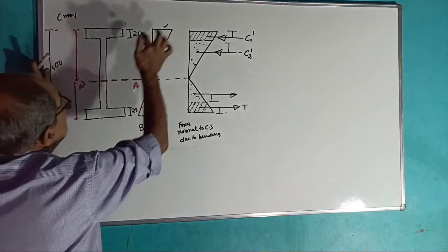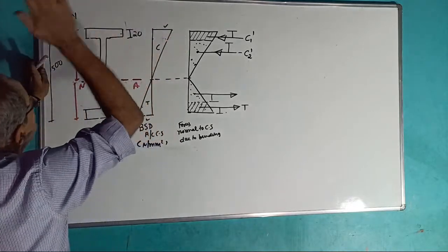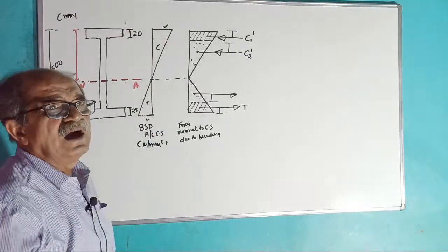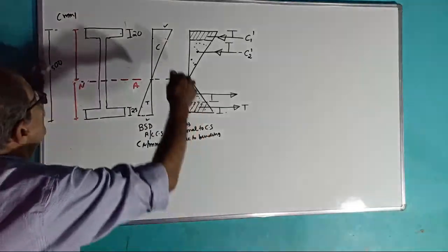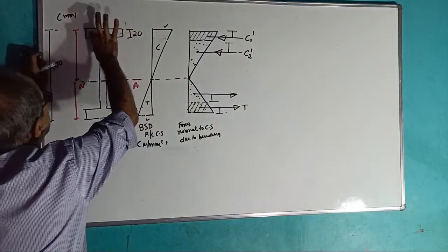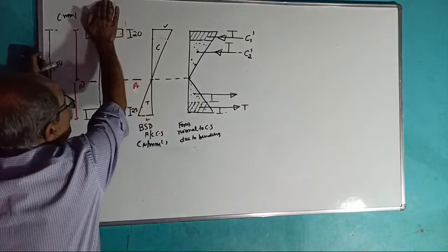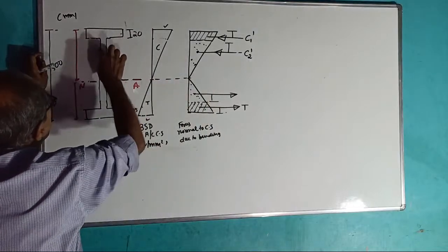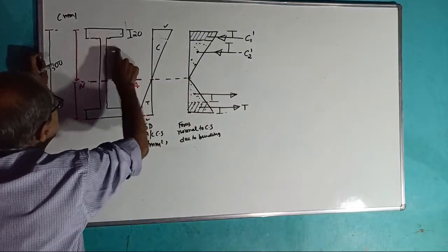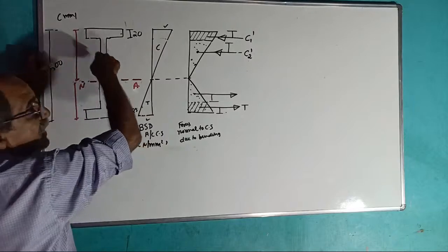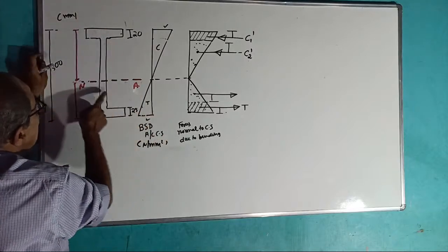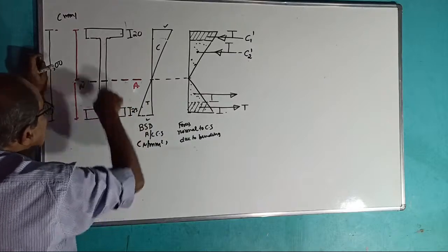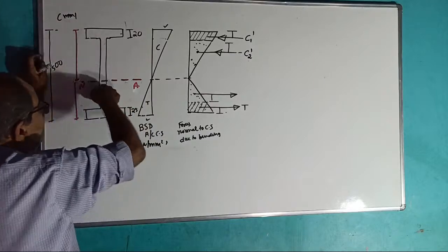Now, this bending stress is actually acting perpendicular to the cross section. This I am repeatedly telling right from the beginning. Because of the stress, the upper flange will have compression. Why? See last class, sagging beam. The portion of web below the flange, above the neutral axis, is also in compression. And the web portion below the neutral axis is in tension.